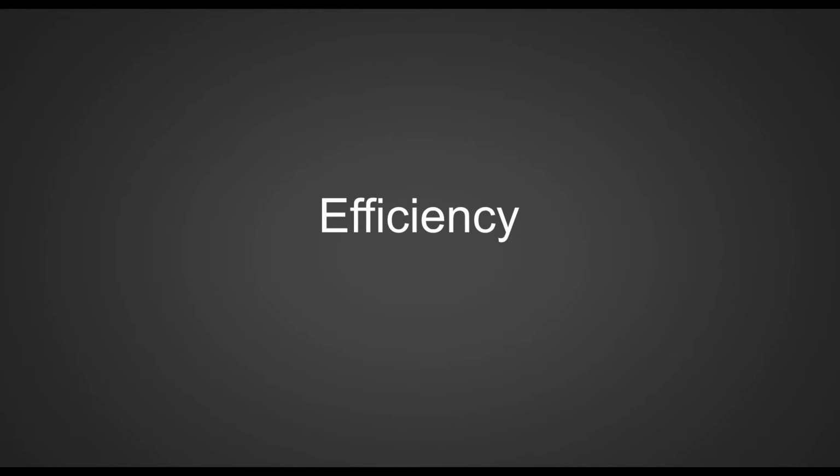So efficiency. How to be efficient in SOLIDWORKS can be a daunting task, right? There are a wide variety of ways to go about workflows, commands, customizing, and ways to get all these things accomplished. There are typically at least 3 ways to access a command in SOLIDWORKS, if not many more. Things can be accessed from the command manager, the drop-down menus, mouse gestures, shortcut keys, right mouse button clicks, the search bar, just to name a few.